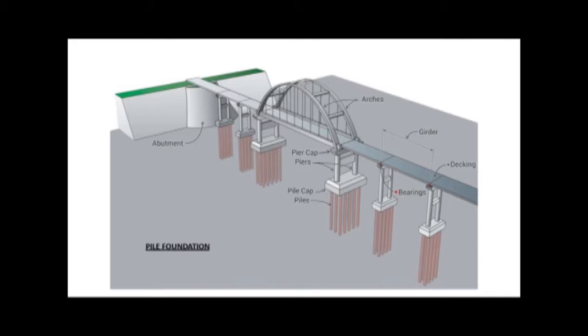The caisson foundation is very much susceptible to tilting. If you have ever visited an ongoing bridge construction site, you might have seen huge stacks and piles of large concrete cubes, and those cubes are used to rectify the tilting of the caisson foundation.